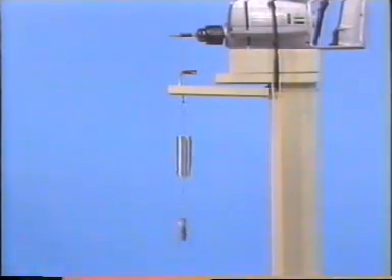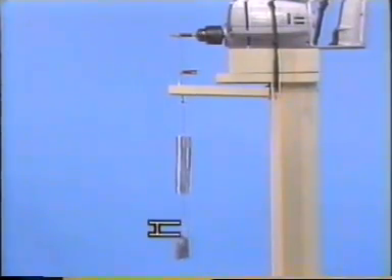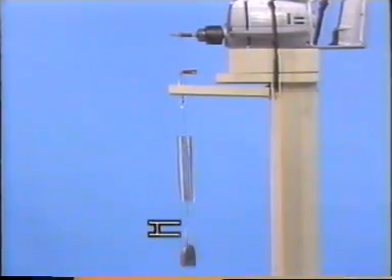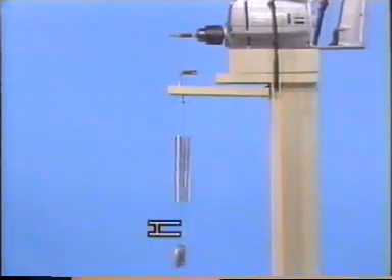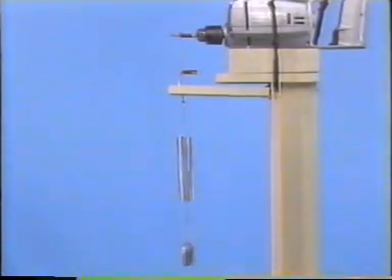Now, we will increase the speed of the drill until the frequency of the oscillation that it produces reaches the natural frequency of the vibration system. You will notice that the amplitude of the oscillation increases. When a system is vibrating at its natural frequency and a vibration of the same frequency is added to it, the amplitude of the vibrations becomes larger. This phenomenon is called resonance. The source of a vibration, such as the electric drill in this example, is called a vibrating force.